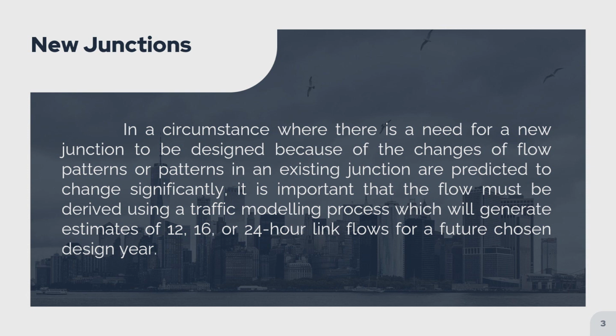Recalling what the average annual daily traffic means, it is the average 24-hour volume at a given location over a 365-day year. The average annual hourly traffic is then calculated by dividing the average annual daily traffic by 24 and then factored to represent the appropriate highest hourly flow using derived factors. Tidal flow is also taken into consideration. Generally, a 60 over 40 split in favor of the peak hour direction is assumed. Turning proportions are also estimated so that the junction can be designed.